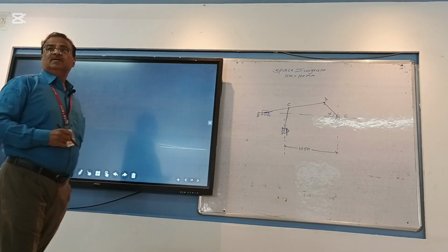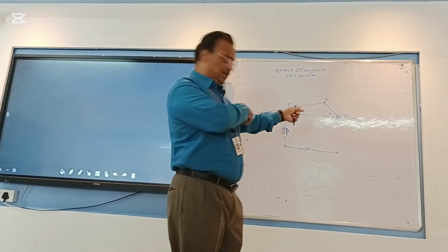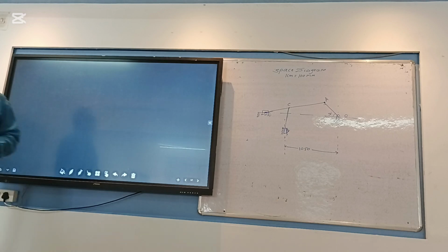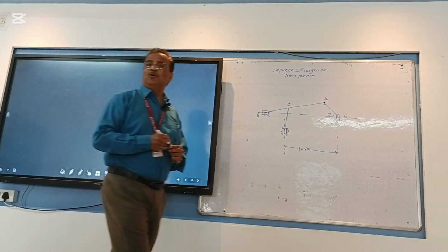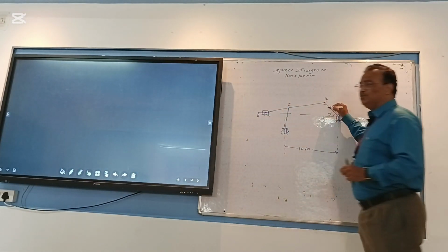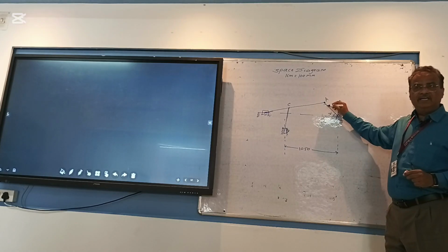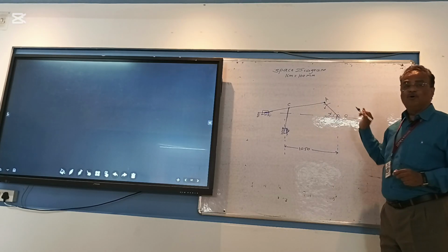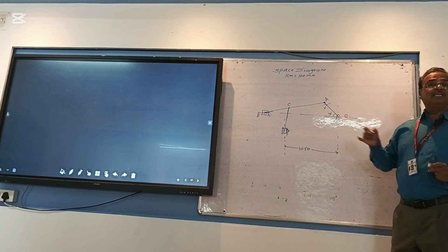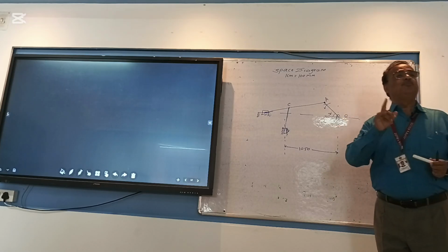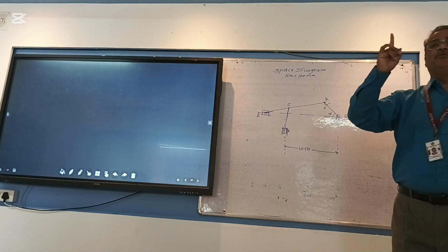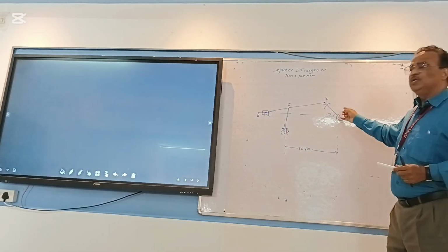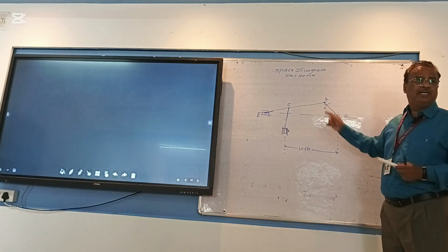Already I told that after finishing the space diagram, always you have to perform one calculation to begin with the velocity polygon. What is the direction of rotation of this crank? Anti-clockwise. What I said, to begin with the velocity polygon, you must know the direction of rotation of any one link, crank, first link, crank. Right? So direction of rotation of the first link is anti-clockwise direction.